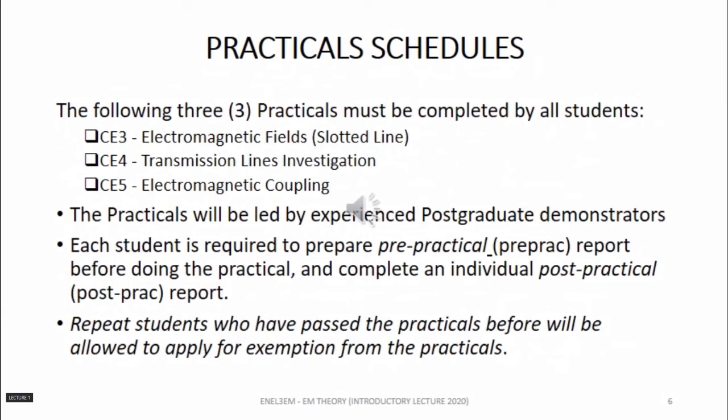We'll determine the resistance per unit length, the inductance per unit length, that's per meter, the capacitance per unit length, and the conductance per unit length. So we'll do this for each of the two lines, and we will use this to determine the characteristic impedance of the line.